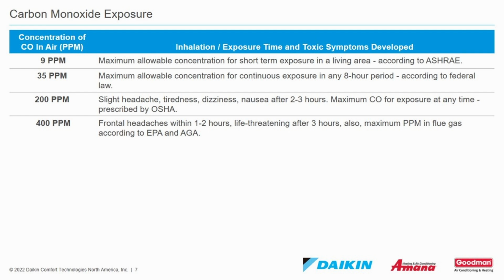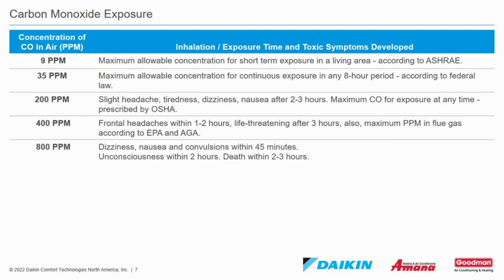400 parts per million. Frontal headaches within 1 to 2 hours. Life-threatening after 3 hours. Also, maximum parts per million in flue gas, according to the EPA and AGA. 800 parts per million, dizziness, nausea, and convulsions within 45 minutes, unconsciousness within 2 hours, death within 2 to 3 hours.